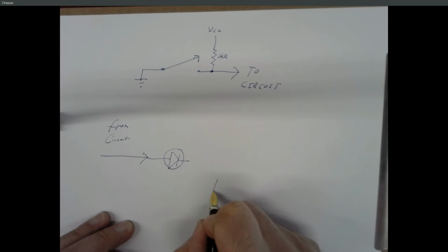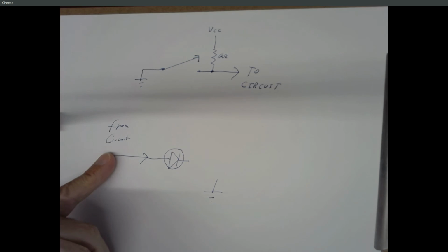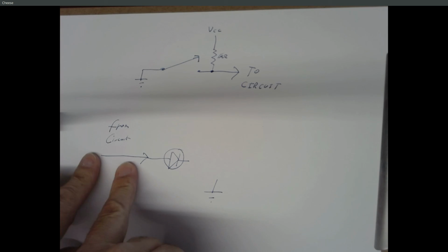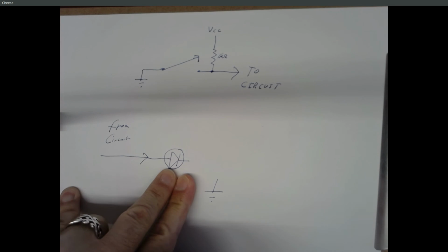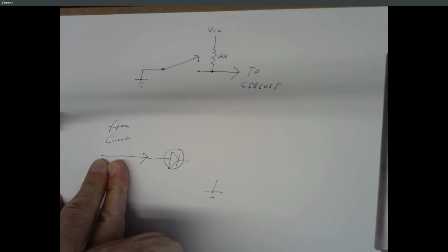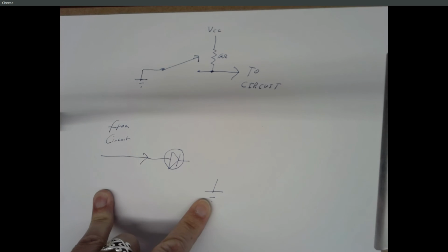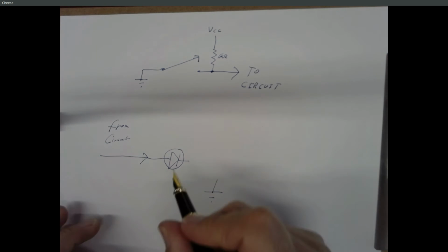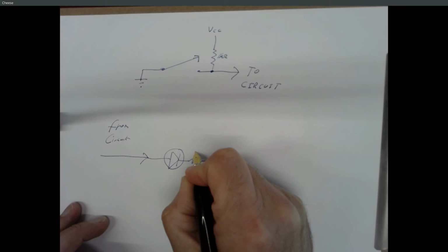And theoretically, we can take the other end of the LED and connect it to ground, and that may work or it may destroy the LED, depending on how much current can come out of this circuit at this point, because these can only handle a little bit of current. And if I were to hook this up to, say, a high volt power supply, run it through an LED to ground, it'll flash and pop and it's done, because it got too much current. So to make sure we never get too much current, we throw a 1K resistor here in series.